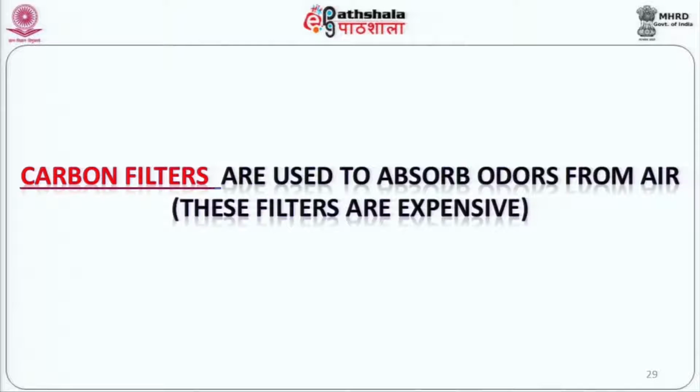But just imagine being a few hundred feet below earth, keeping yourself in a bomb-proof shelter and liberating pollutants from a personal body. At that point of time, one reduces the quantity of fresh air required and tries to control odor by using carbon filters. These carbon filters are expensive, they can be regenerated, but they have limited usage for these kind of applications where it's expensive to take fresh air to dilute the pollution.